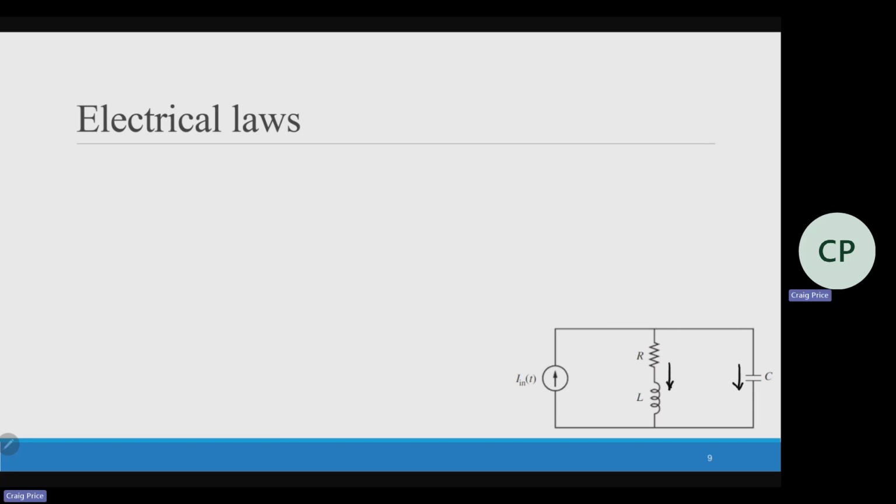In this case, I have an input current that's going to split into two different currents. So maybe I call this one inductor current, call this one capacitor current. Anytime I've got a node, it's going to split. So I would create a KCL right here, where I_in is equal to the sum of those two.